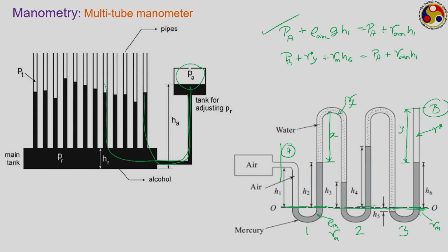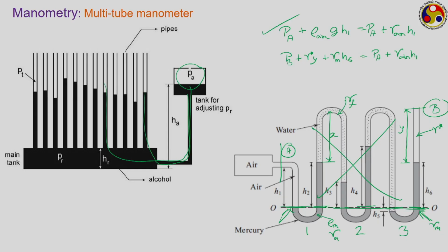So, pressure at all these points has to be equal to each other, as this is a connected system of fluid, and so we can bypass this entire intermediate portion, just focus on this starting point and this finishing point, or the first arm and the last arm, and get a value of this reading just by knowing the values of H1 and H6 and the properties of all the involved fluids. So, this way, despite a visually very complicated manometer structure, our calculation may not be that complicated at all. Now, let us use this concept to solve a few very simple manometer based numerical problems.